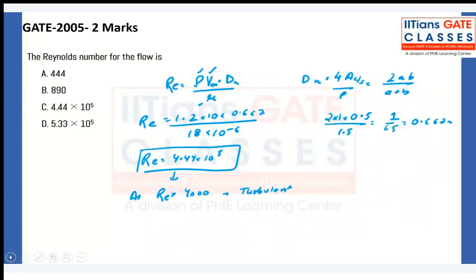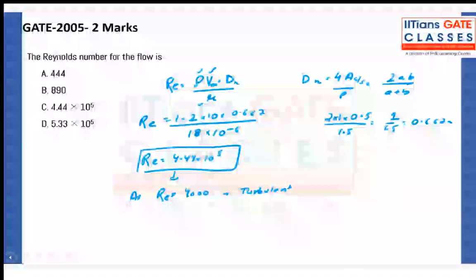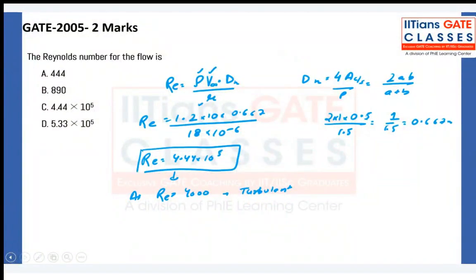I am very sure we have to use surface area. Probably this is one other way of doing it. I am not aware of it. Okay, just see if you multiply DH into L. Area coming was 0.2 meter square, sir. Area is 0.2 meter square. Tell me what did they do? They multiply hydraulic diameter into what? They take the height. They convert the rectangular section into the hypothetical cylinder by DH, sir.